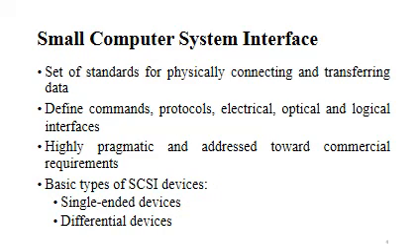Small Computer System Interface, in short SCSI, is a set of standards for physically connecting and transferring data between computers and peripheral devices. The SCSI standards define commands, protocols, electrical, optical, and logical interfaces. SCSI is most commonly used for hard disk drives and tape drives, but it can connect a wide range of other devices, including scanners and CD drives, although not all controllers can handle all devices.